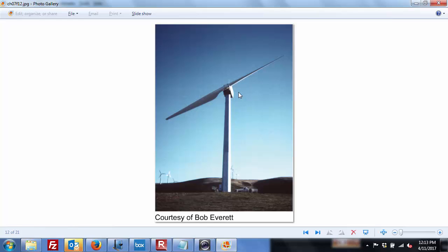As these blades rotate, the angular velocity of the entire structure changes, and you start to get some shimmies. Especially as this spins about its vertical axis, as the wind changes. It's an example of why you might not want a two-bladed design.